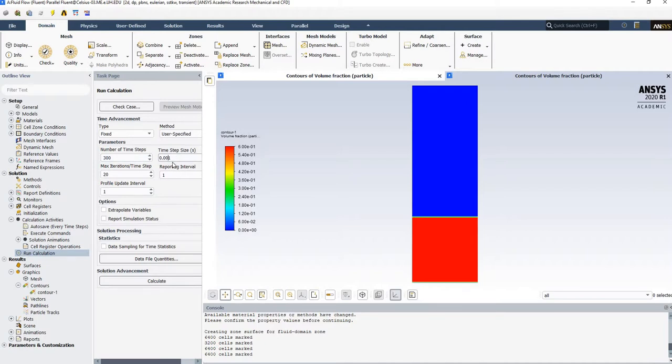But again, if you go to a larger time step like this, Courant number would go really high. And actually the threshold is you don't want your Courant number to go above 1 or 2. You can calculate the Courant number, and it actually shows the Courant number in the console as well. You can check after time step ends, it shows a calculated Courant number.